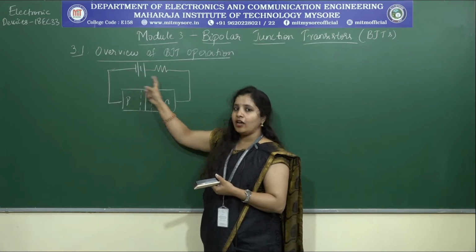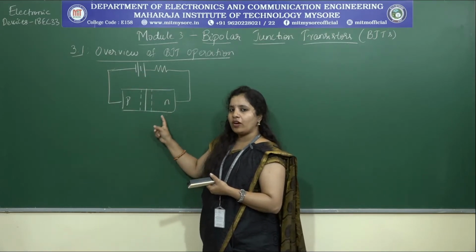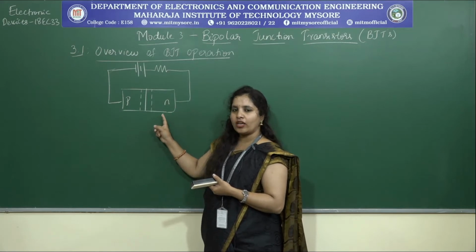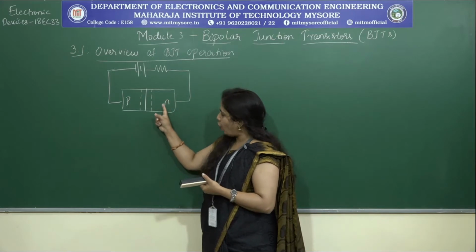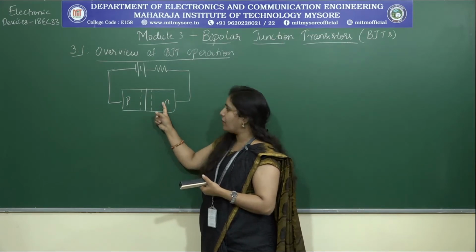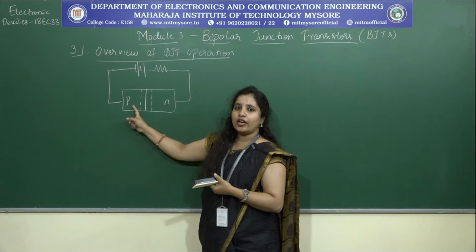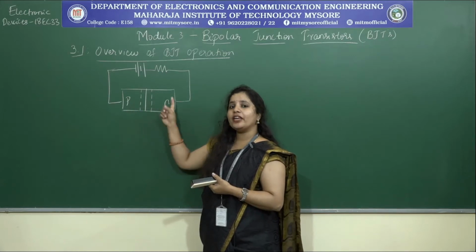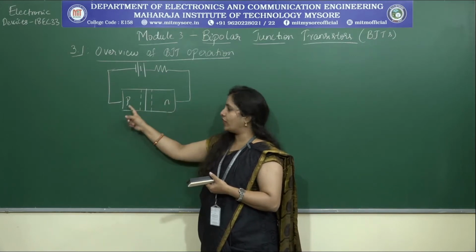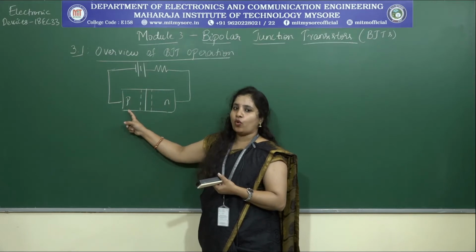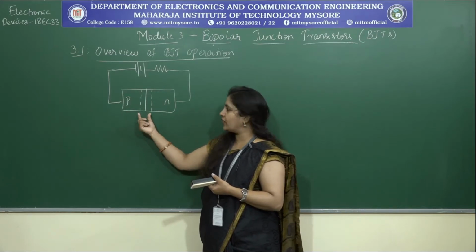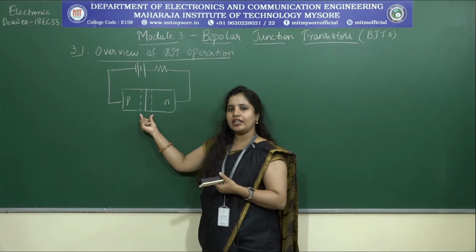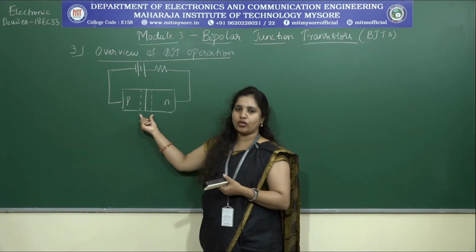The reverse current that is flowing in reverse bias is all about how often the holes present in the n-type get swept through to the p-type. It is not about how many of them are getting moved into the p-type material. So this has nothing to do with the strength of the electric field present in the junction that we have seen in the previous session, right?